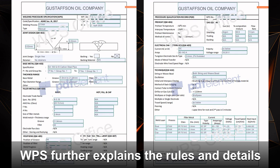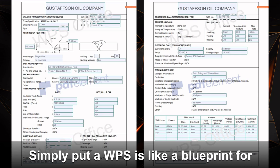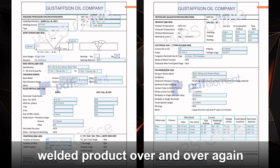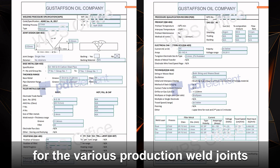WPS further explains the rules and details of the test and how the pieces should be assembled. Simply put, a WPS is like a blueprint for welders to produce the same quality of welded product over and over again. Once a WPQR has been produced, the welding engineer can write qualified WPS for the various production weld joints that need to be made.